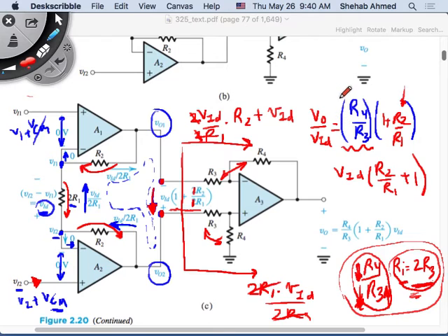Since I already got rid of the common mode signal, making R4 and R3 so equal to each other, with precise resistances, is no longer very important anymore.